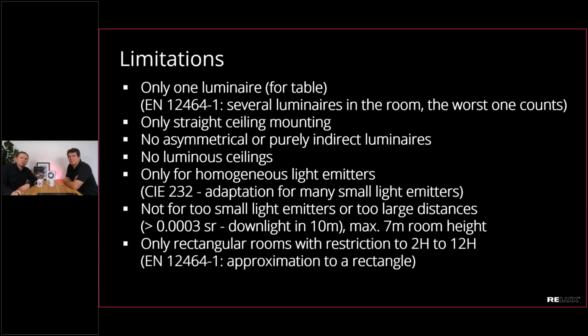Okay, then of course, just rectangular rooms work with the table. So we have just these 2H or H-related room dimensions, and this also comes to an end. Most rooms, of course, fit in this scale, but you potentially have a really large hallway, and then it might not fit into this table. There's also a hint in EN 12464: we can just approximate one rectangle into the room. This is okay for 12464. If you have a polygonal room, just make a bounding box of it and use it.